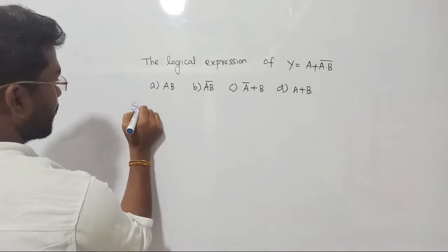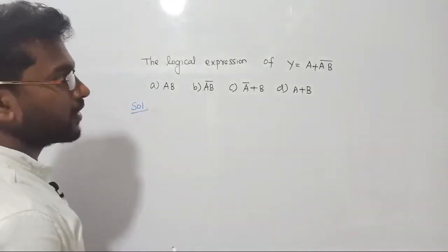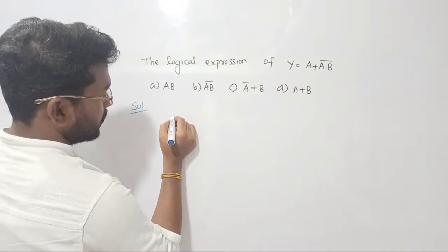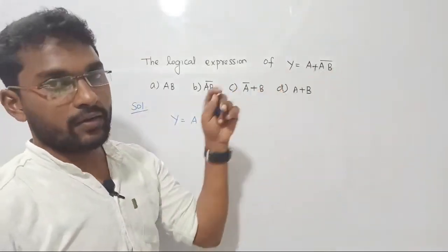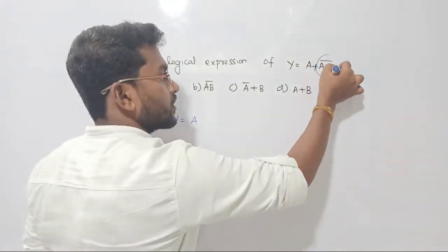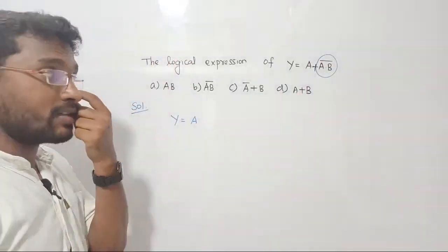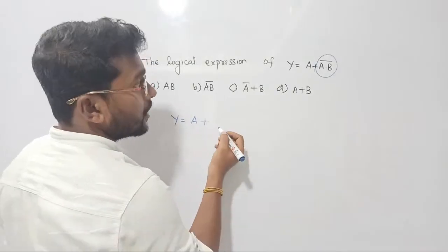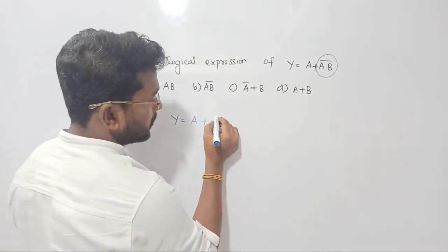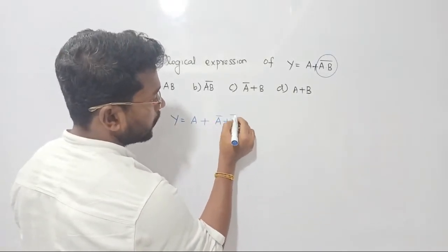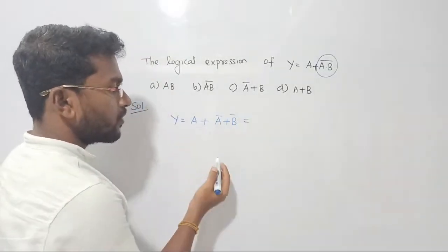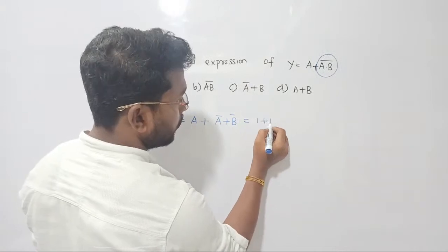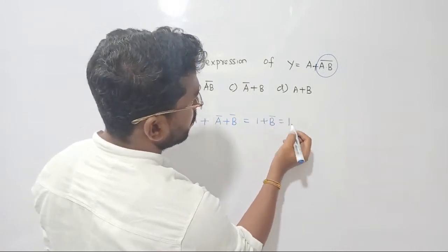Someone of you had given the answer, right? I'm really feeling very happy. Let's take this one. Actually, we cannot directly apply. First of all, I have to break this bar. A dot B whole bar. Shall we apply De Morgan's? According to De Morgan's law, it can be written as A bar plus B bar. What is the answer here? See there, A plus A bar will become 1, right? So 1 plus B bar is equal to 1, you know.